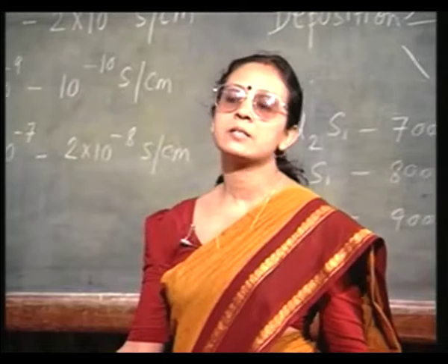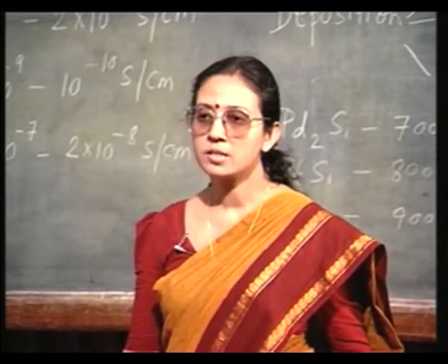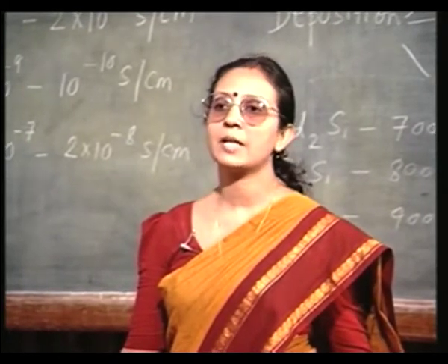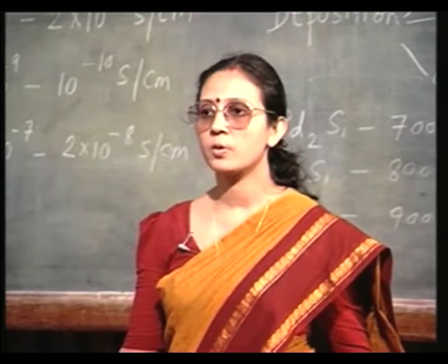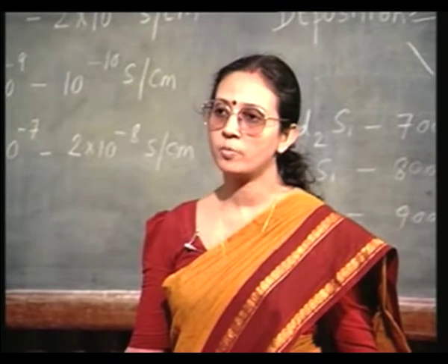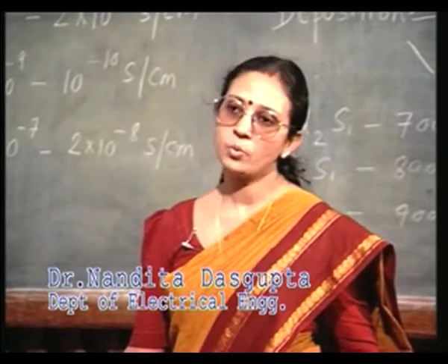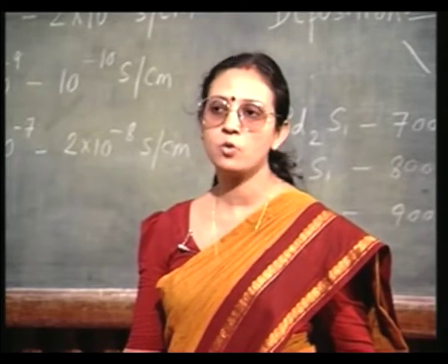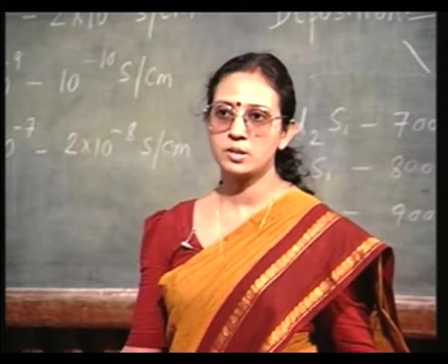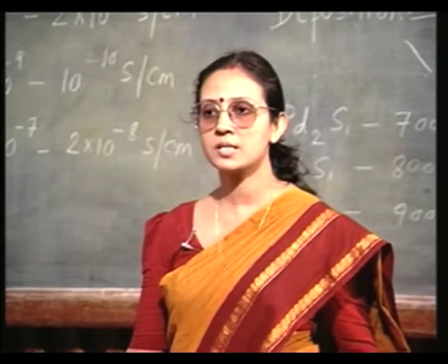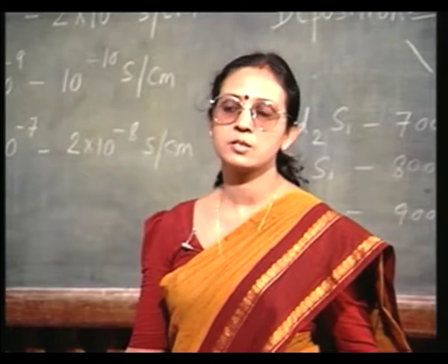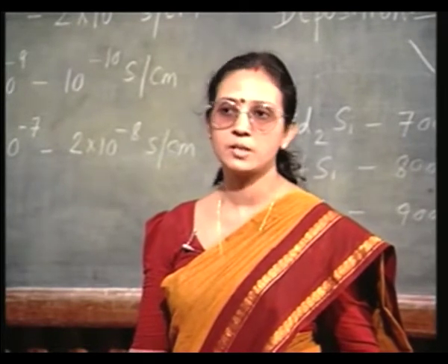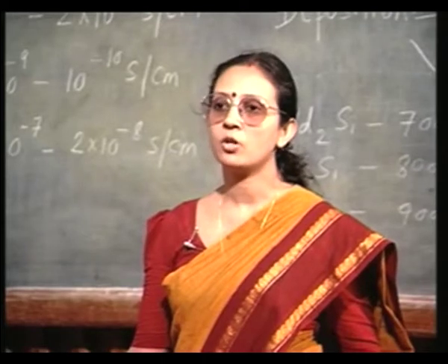Okay. We will look at an integrated circuit bipolar junction transistor, see what its features are, and then we will see how the performance of this transistor can be improved. What process modifications are needed to improve the performance of this bipolar junction transistor, and thus we will trace the development of the bipolar junction transistor fabrication process, how from the first old junction isolated NPN transistor we have come to today's high speed polyemitter poly based transistors used in emitter coupled logic, how the performance enhancement has been achieved by the advent of process technology.